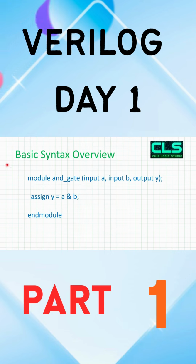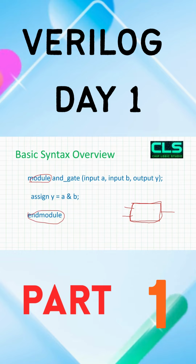So let's start with our Verilog. You can understand an AND gate like this. For example, suppose we don't know what an AND gate is. We know that an AND gate has 2 inputs and 1 output. This outer box is our module and endmodule. We will cover everything with this. This box is our module and endmodule. You can understand it like that. And we will describe its input and output. A and B are inputs. We describe the pins of that module, A and B as inputs, and the output as Y.